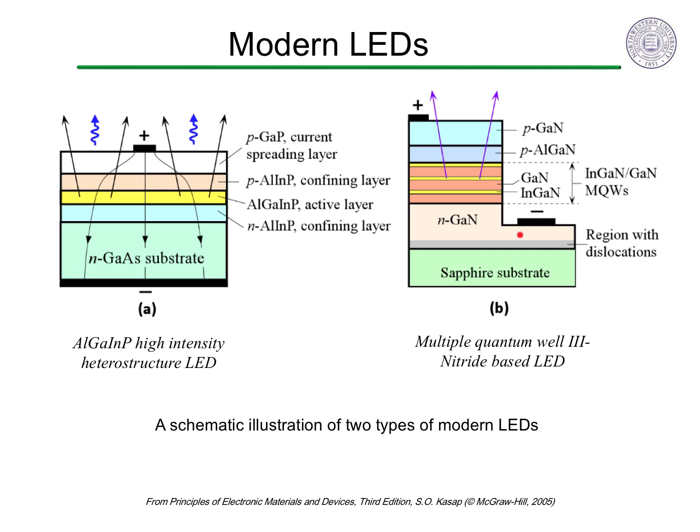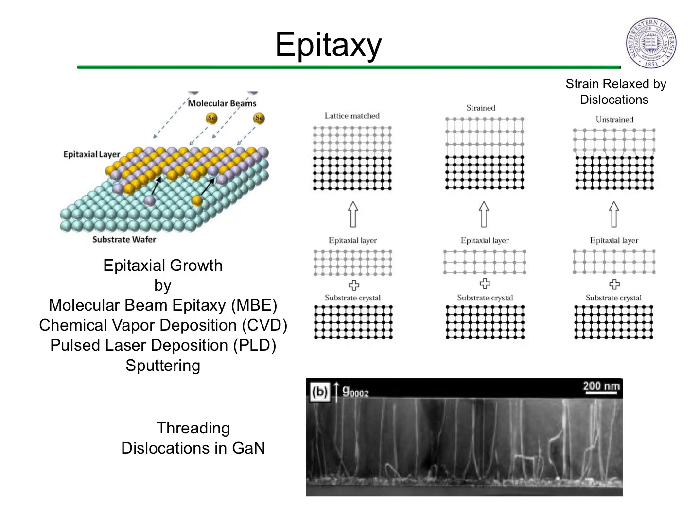The substrate also enforces all the layers to be lattice matched, meaning that all the atoms are in a specific crystalline arrangement with the layers below called epitaxy. To keep the LED efficiency high, the defect density needs to be low because defects act as non-radiative recombination sites and reduce charge carrier mobility.